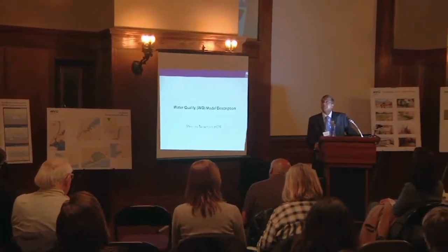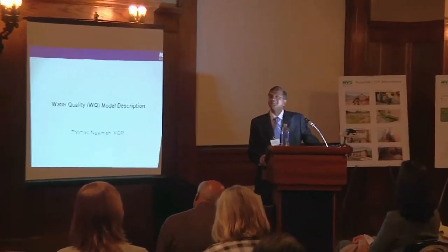It becomes a key factor during dry periods. When you have groundwater infiltration coming into the sewer system, we do see that, especially in the CSO control facilities, which are really at the end of a large drainage area, like Flushing Creek tank, which has a tributary area of 6,000 acres. So it gets in the range of 6 or 7, 8 million gallons per day as groundwater infiltration.